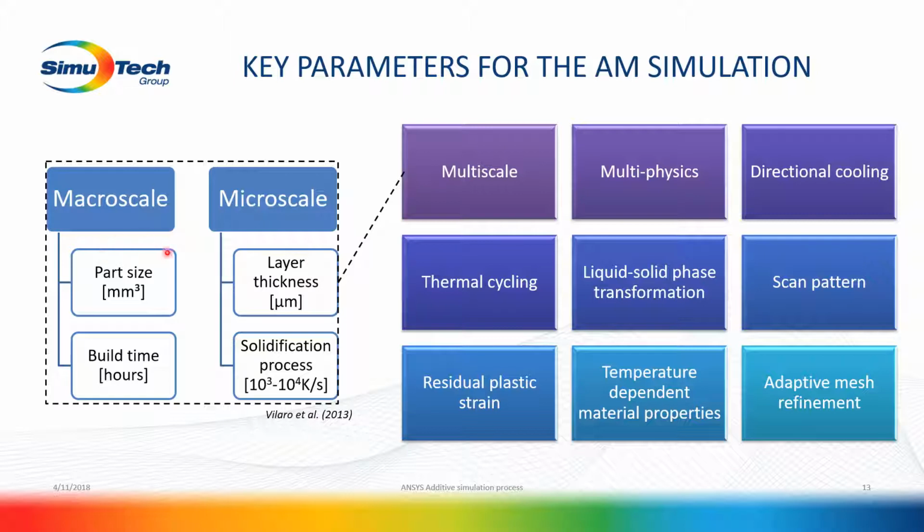So we really have this clash in terms of physical dimension, because in terms of simulation, if we want to simulate that correctly, our mesh would have to be as fine as maybe half a layer thickness, and you can just imagine what the size of the mesh would be if we want to print a part that is 10 or 20 centimeters high. So this is a good example of the multi-scale challenge we are facing.